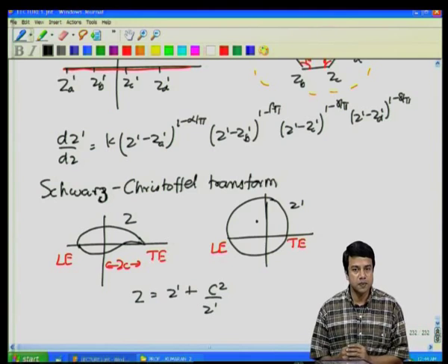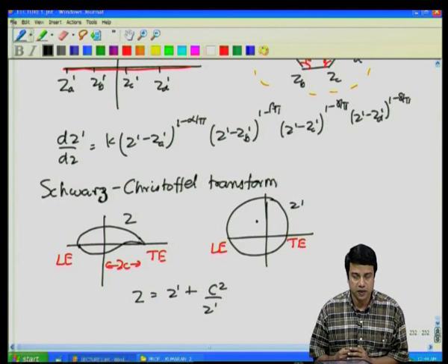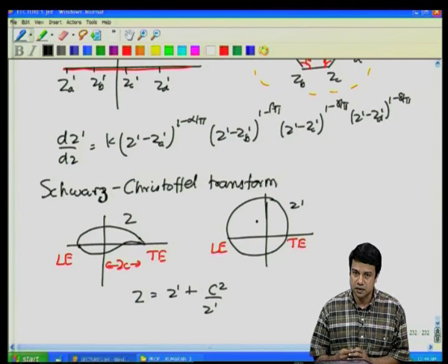So, this completes our discussion of potential flow. I first derived the equations for you for an inviscid irrotational flow, and I showed you that you get 2 scalar equations. One is for the velocity potential itself, because the vorticity is equal to 0, therefore, the velocity can always be expressed as the gradient of a potential. So, one equation we get is the Laplacian of the potential is equal to 0, and then the Bernoulli equation for the pressure. Then we solved it for simple cases.